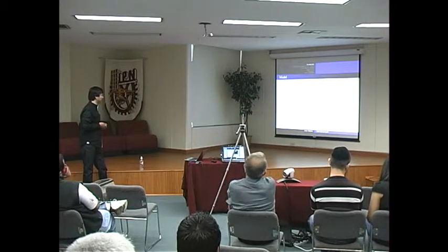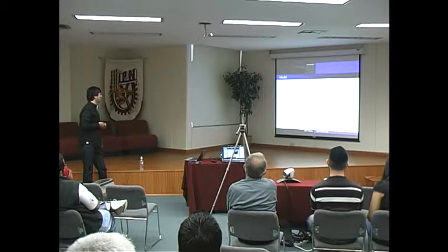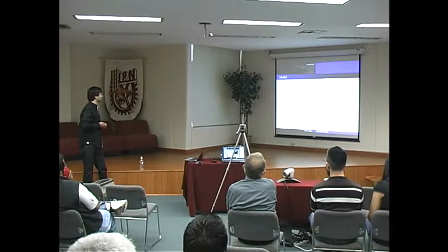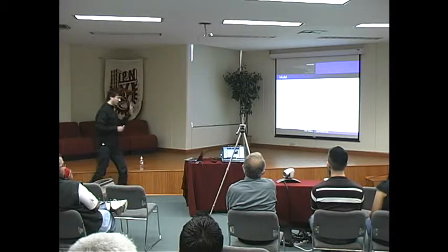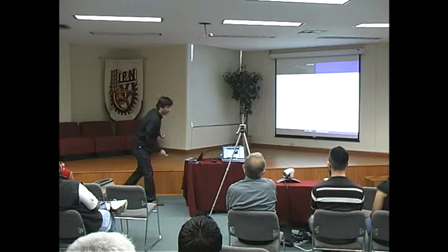The task of the switching is to close the circuit, then the inductor is going to be charged with a current, and when the switch passes to this position, the current that is loaded in the inductor is going to be transferred to this circuit. Essentially, this is the way that this system works.